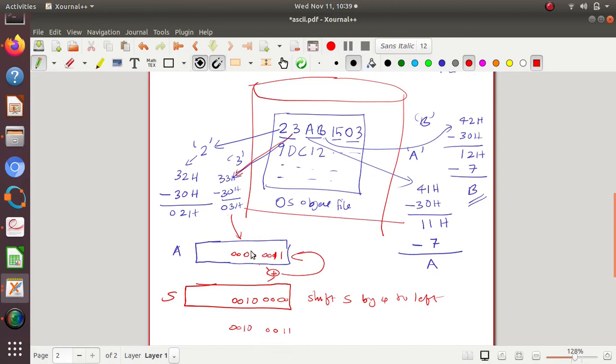So that result is copied to here. So we will get 0 0 1 0 0 0 1 1. Now A contains, what is this value, 2 3. So the hexadecimal value 23 is present within A, and we can load this value into our memory RAM. What can we do into the RAM? At the required location, for example if it starts from 80H, we can load 23 there, store 23H.